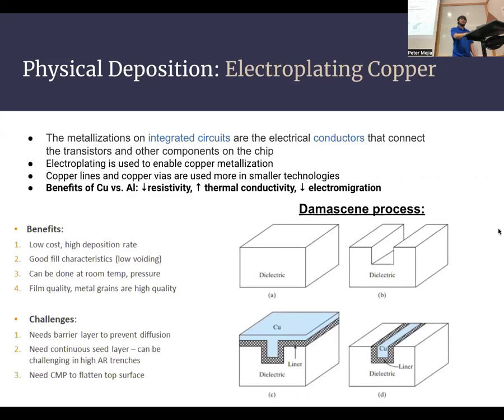Although I think we'll be doing sputtering for the metallization. I think so too, yeah. Sputtering is definitely what we'll do. There's an advantage to that in that there's a lift-off process. Oh, true. Yeah, we're gonna talk about that next. We take advantage of that property of sputtering in order to basically avoid etching metal. All of these we're gonna go into more on Thursday, so I'm kind of gonna speed through the rest of them, just because it's definitely past 6 now.